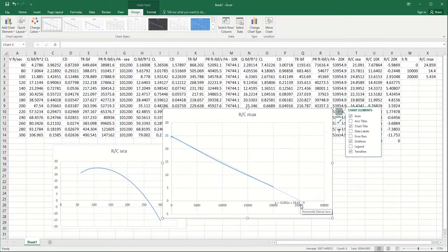Now there's something called a service ceiling, because all you can do is asymptotically approach this absolute ceiling. As you get closer and closer to the ceiling, your rate of climb goes lower and lower. So you'll reach a point where it might take the next 10,000 years to actually get all the way up to that, and you'll run out of fuel before then. So there's something called the service ceiling, where the rate of climb is 100 feet per minute.